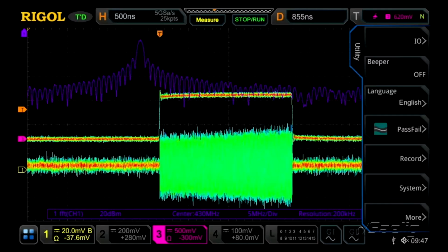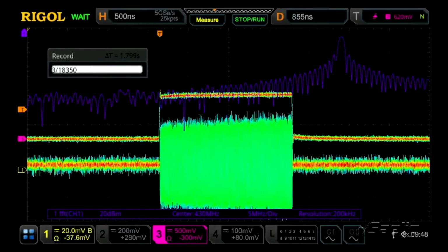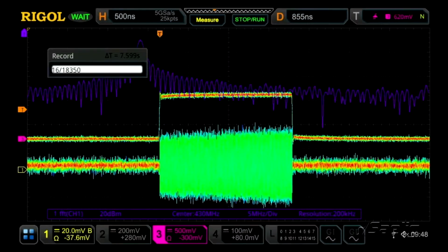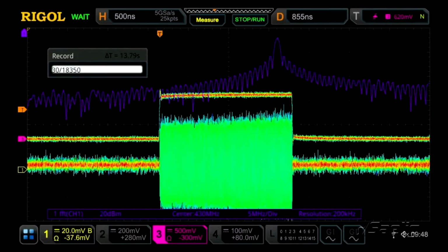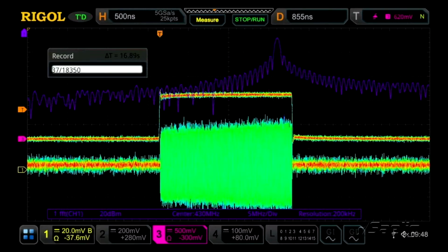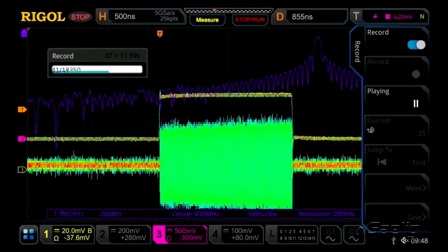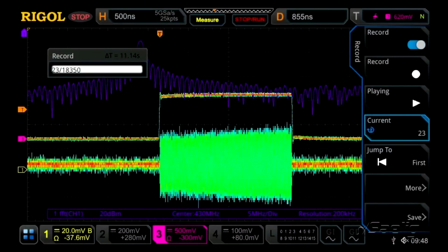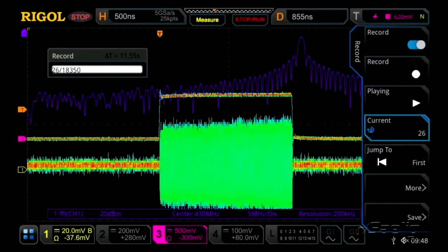Well, one way is to use the record mode capabilities within this scope. This will let you record thousands of frames of activity. Each pulse that is triggered causes a frame. We're capturing those frames and using the sequenced and segmented memory here to do further analysis. Whenever we feel we have enough, we can stop that activity. Then we can play it back either as a movie, or look through sequences of frames. Now we can look at each bad pulse or double pulse and ask, what's causing that activity, what frequency is that at, what's the pulse sequence and timing, and see how that all works together.